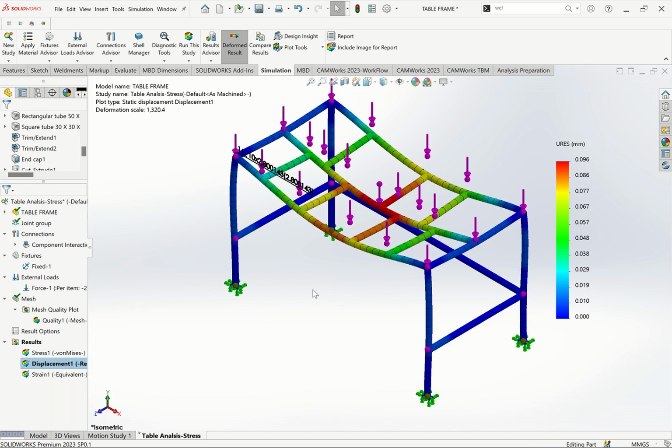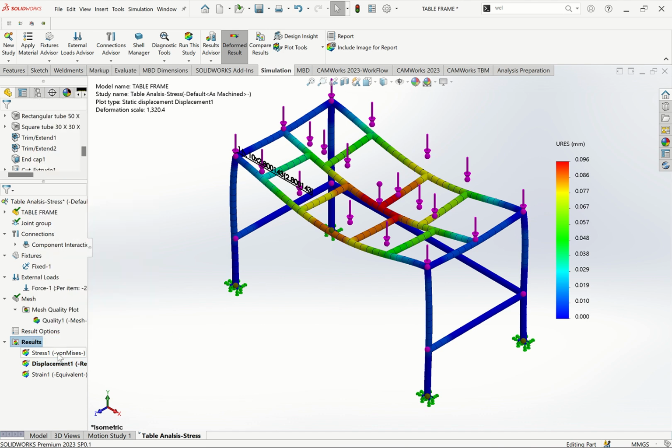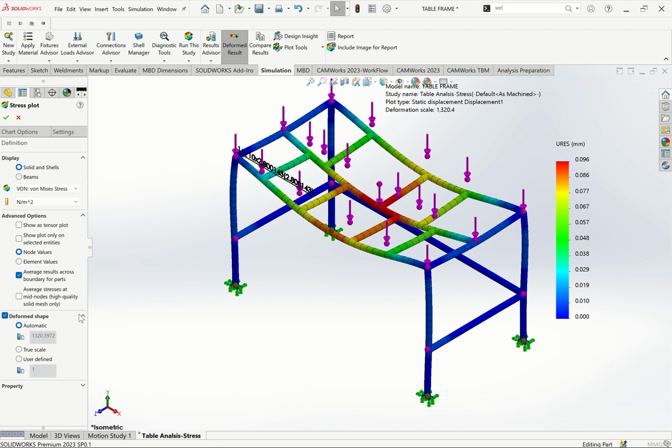Okay, you see it has changed. The reason why here it is bending too much is because there's no support going down. At the far end here, there's a support going down, but here there's no support going down. But I can do what you call, in these results, I can come to this, edit the results, stress analysis. Then I say, give me a true value. I'm using a true scale.